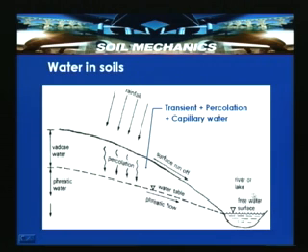This is a typical schematic representation of a river or lake, and in this zone there is transient percolation and capillary water. This capillary water occurs because of the phenomenon we discussed just now, surface tension, which is a property of the fluid that sucks and draws the water into the pore spaces of the soil above the groundwater table, with the groundwater table as its source.